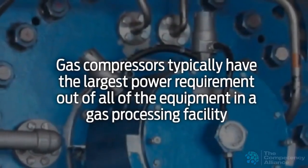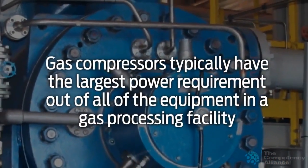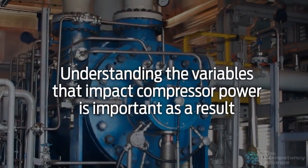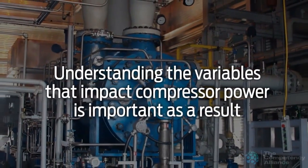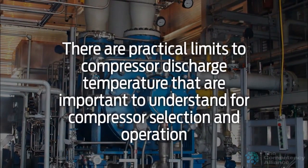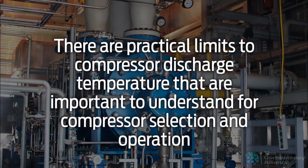Gas compressors typically have the largest power requirement out of all of the equipment in a gas processing facility. Understanding the variables that impact compressor power is important as a result. There are practical limits to compressor discharge temperature that are important to understand for compressor selection and operation.